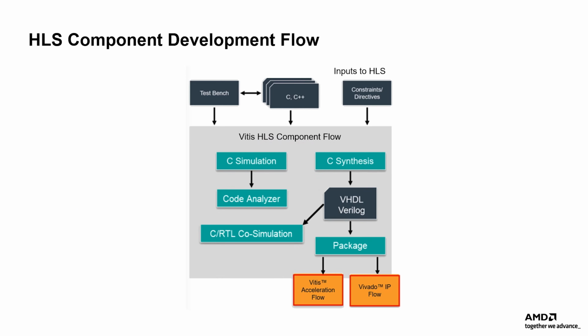The Vitis Unified IDE and V++ Common Command Line provide the ability to create an HLS component using bottom-up design techniques to ensure that the component meets design requirements before integrating it with other elements into a system design. Here are the steps for developing an HLS component from a C++ function.